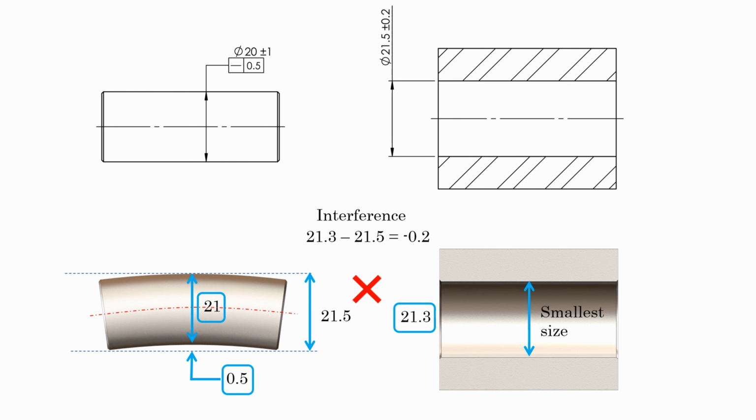So as you've seen, the relation between geometric tolerance and the extreme boundary of a feature of size is crucial. Even though these were very simple examples, we only defined one geometric control over the feature of size. But in real-world design, especially in complex assemblies of machines, we often define multiple geometric tolerances on a single feature of size.